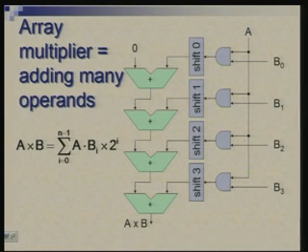Here also the signals propagate through various adders, but there is no storage involved. So, there is some advantage in terms of speed. Such multipliers are called array multipliers for natural reasons. What we will try to see is how we can speed up such an array multiplier. There are many different approaches for multiplication. You can actually have tree multipliers. For example, you are basically adding 4 terms, rather than adding them in cascade.